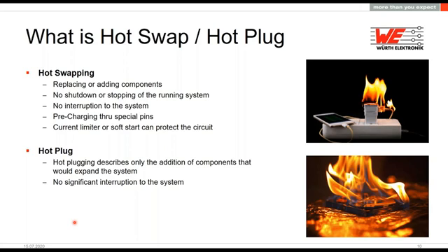Is the under voltage lockout, over voltage lockout correct? And this is why this feature is really important. When you compare it maybe to the wireless power, there's also some handshake to check if it's a valid receiver, that there is no foreign object inside the transmission and so on.